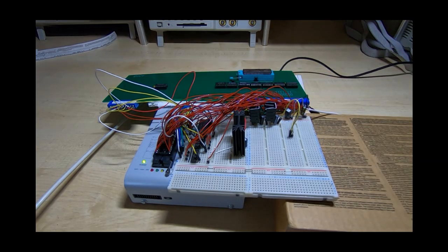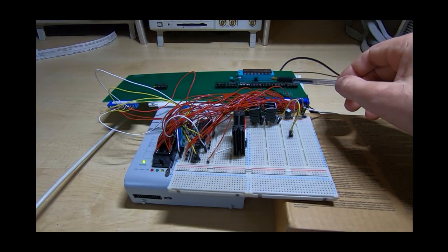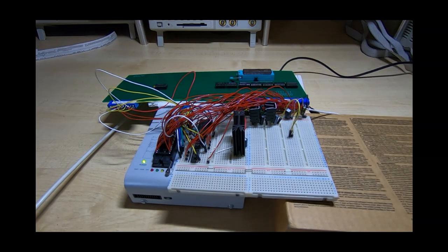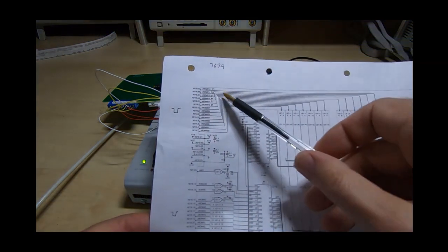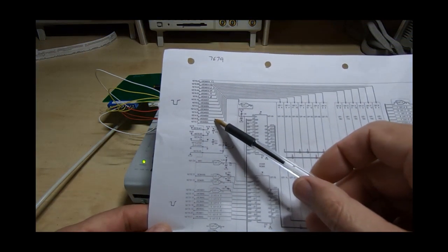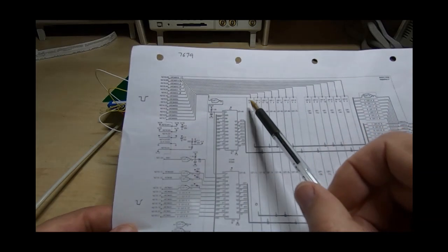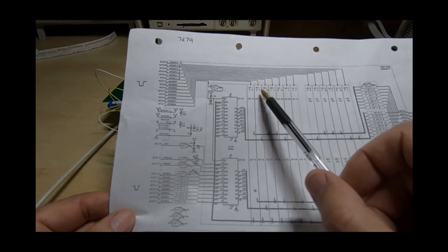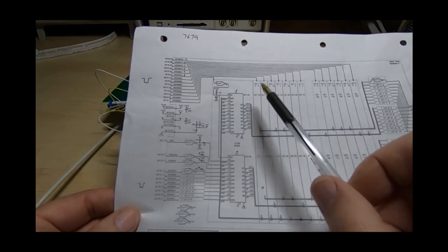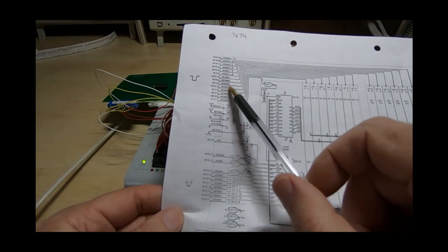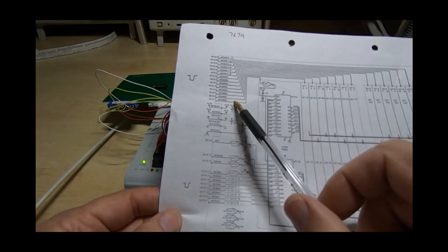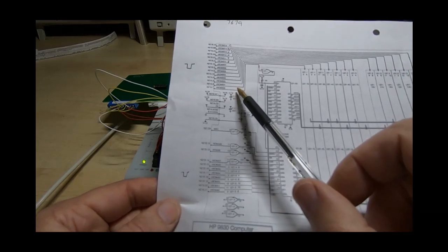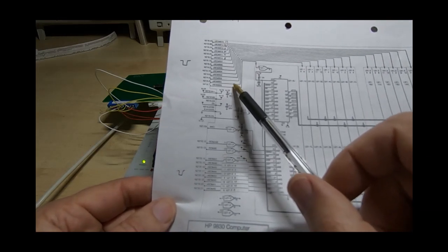So firstly, I've constructed a 16-bit priority encoder, and what that does is it takes the 16 lines that come from the encoded ROM address lines. This is where they select the EEPROM banks in blocks of 512 words rather than 1K words as you'd normally expect. And it takes this and turns these lines back into a 4-bit binary address. So these constitute address lines 9 up through 12.